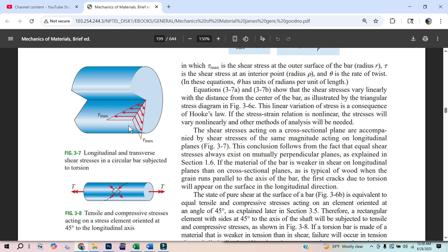So, but yeah, it's just by geometry, this thing rips apart on the exterior. Cool. So we did the angle of twist, circumference. We found that shear angle. Shear angle used Hooke's law to find T max. And now we can go back to the equation to find the actual torque. And that was the whole problem.